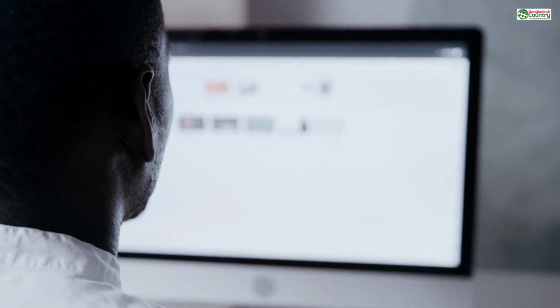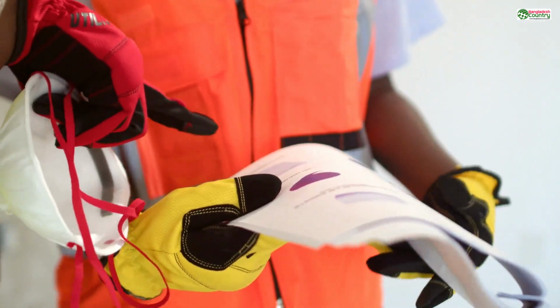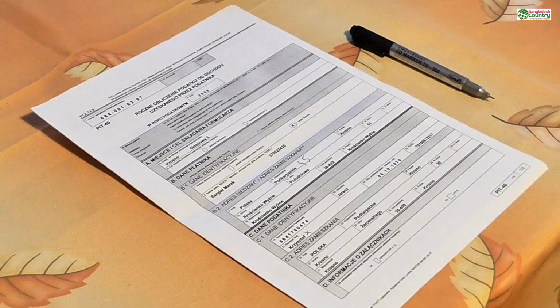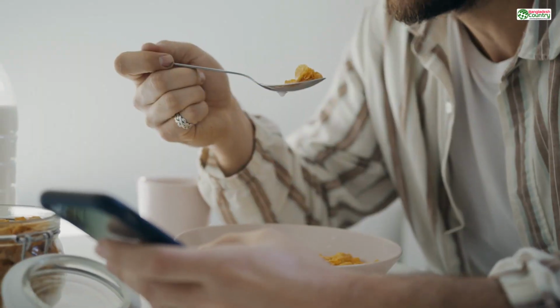Here's the most important piece of advice in this entire section. Every single online 3D printing service has a document on their website called Design Guidelines. It might be called Material Specs or Technical Information. Find it, read it, memorize it. This document is your Bible. It will tell you the exact minimum wall thickness for every single material they offer.